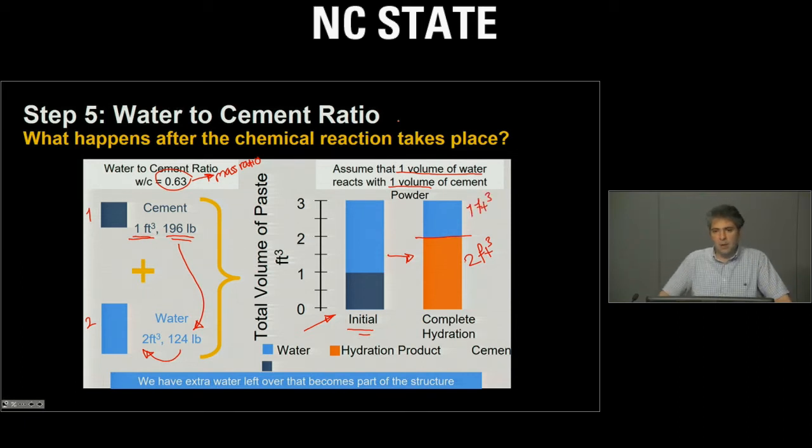of extra water. Now, this extra water does not sit on top of the concrete and does not separate itself from the concrete. It becomes big porosity called capillary porosity, remains inside the system and makes the system weak.